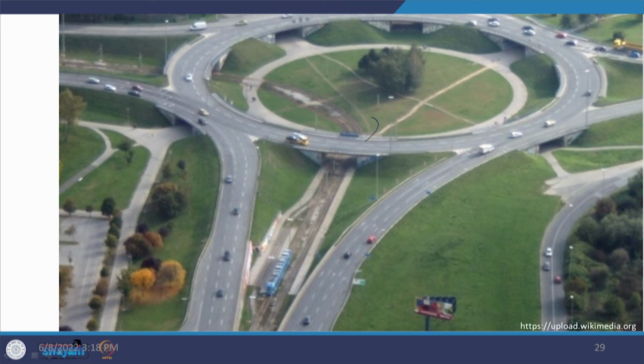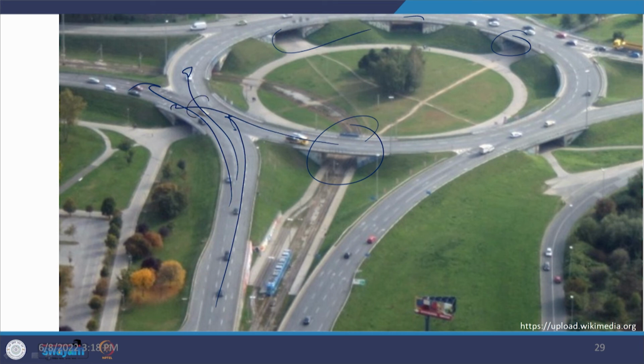This is another case where you can see that it is going up and then the traffic is going at a higher level and then meets or diverges. So, there is traffic that goes from here like this, or there is traffic which gets here. The traffic coming from this one has a conflict here. So, there is going to be a weaving area in this particular section, and here the traffic can go out or keep getting in, further going along the circle. So, merging, weaving, diverging, all of these things are going to happen in this one.